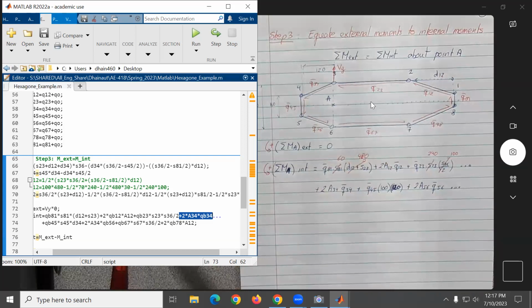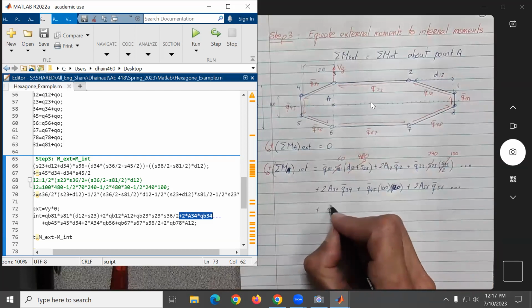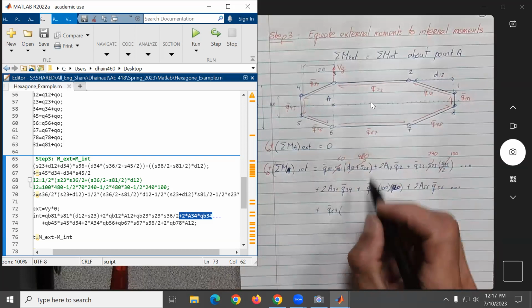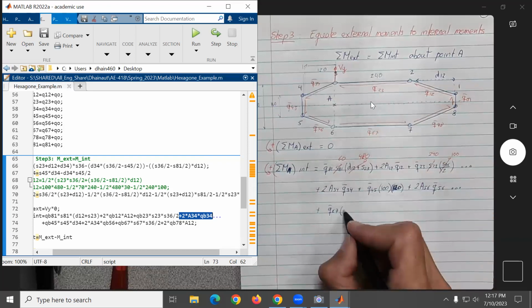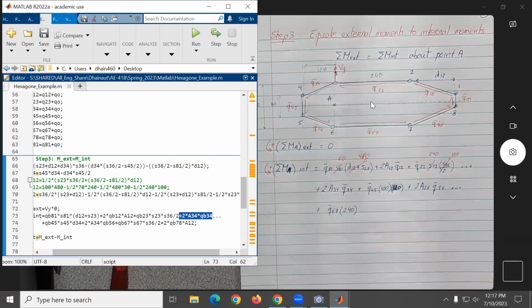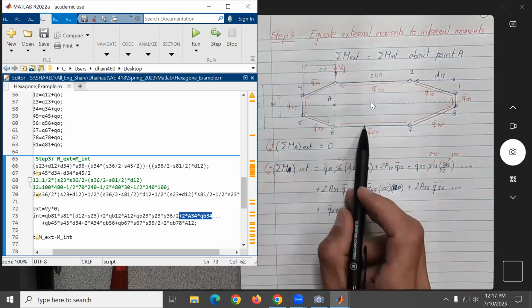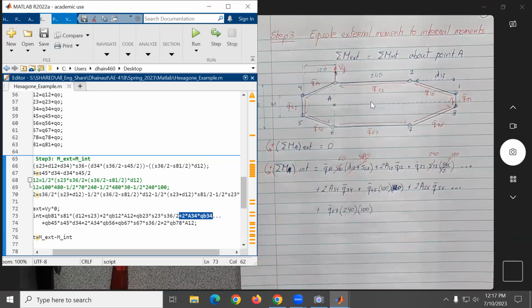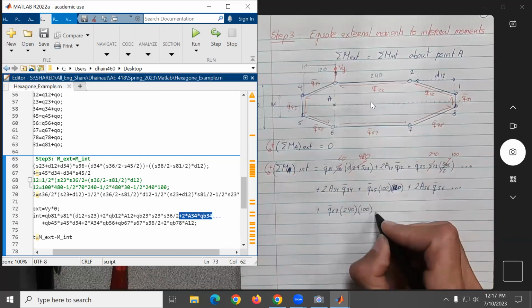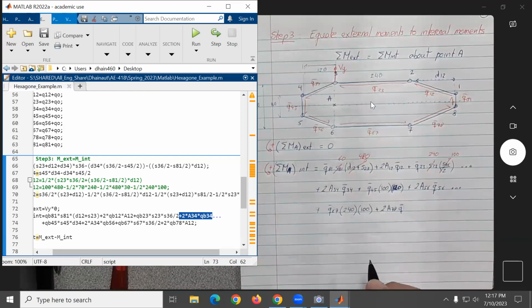Okay, so we have this. Now we go 5, 6 plus Q bar 67. We need to multiply this by what? I think this is 240, no? Is that correct? Yeah. So by 240. Now, so this is the value of the force. What would be the arm? This one will be again the 100, no? Times 100. Okay, for 7/8, we're going to do the same thing, plus 2 times A7/8 Q bar 7/8.